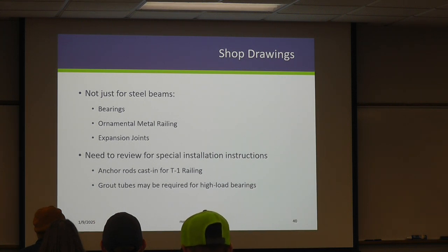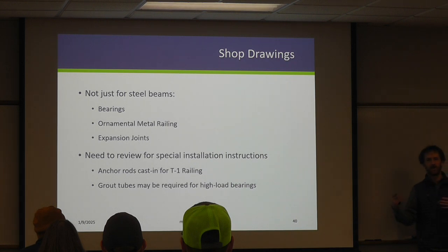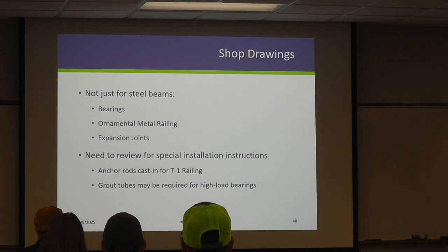So basically, I don't know if anybody's been to the zoo recently, they've got the new monorail trail, and when people walk, they generate a ton of static electricity. You touch the railing to hold you on, and you get zapped. And so we have to provide this electrical continuity now to prevent something like that from happening. Now on our structures, it's more likely going to be stray current from high wires or if there's utilities attached to the bridge. But there's now special installation instructions on how to create that continuity in these rails that the contractor and yourselves need to be aware of.